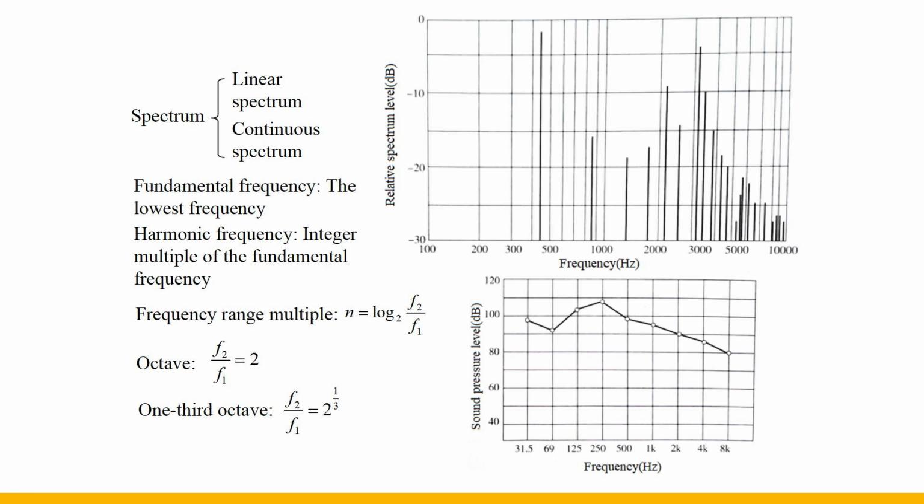The bandwidth of the frequency band can be narrow when the accuracy is required to be high, and can be relaxed when simple measurement is allowed. The frequency bands are divided so that the ratios of the upper and lower bound frequencies are equal. N is equal to the base 2 logarithm of the ratio of the upper bound frequency and the lower bound frequency, which is a reciprocal of a positive integer. Using the logarithmic scale on the frequency coordinate axis to represent the center frequency of each frequency band, it can be divided at equal distances.